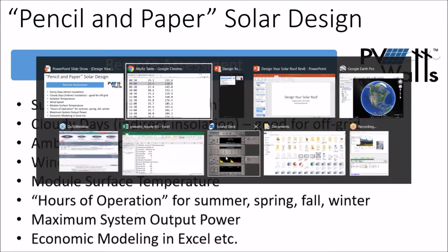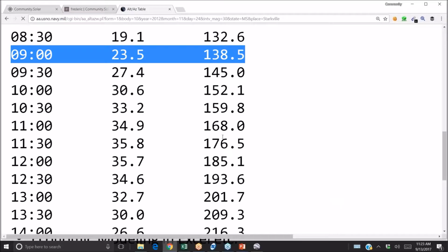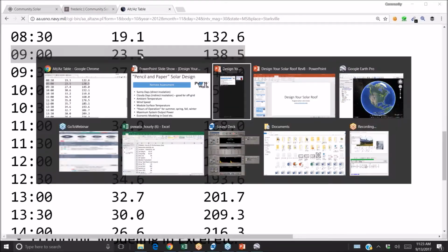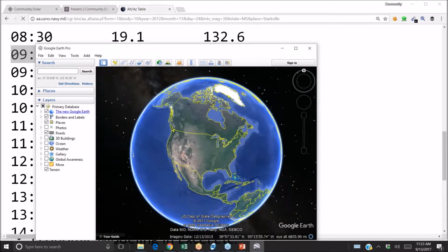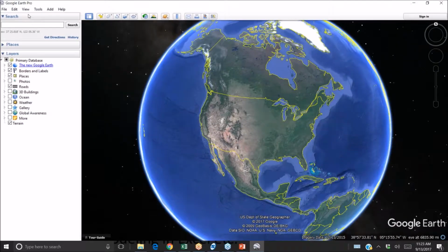And then for that matter, when you say, well, what about the ruler tool dimension for my rooftop? Is that going to be accurate enough? It is pretty accurate. I mean, you can trust the dimensions. But anyway, you're still leaving at least 3 feet off the sides and 3 feet off the top of the roof for fireman access. And so if you're off by an inch or two, that's not the end of the world as far as remote assessment goes.